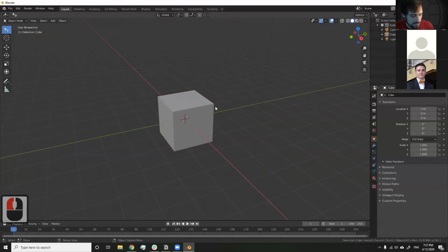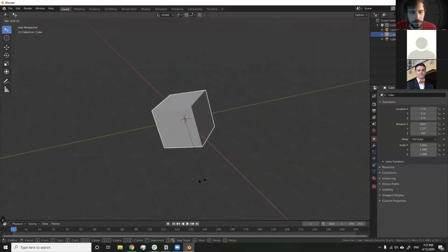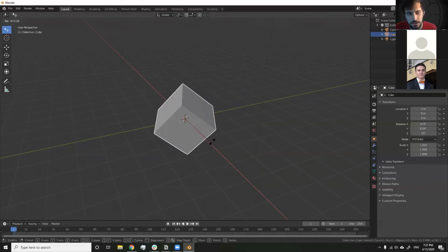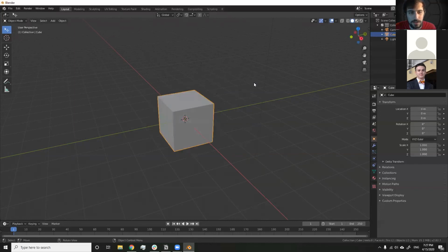The next shortcut that we want to go through is hitting R, which will allow you to rotate an object. So if I just select the default cube and then hit R, it's going to kind of orbit around its center of mass at the center there. You can see that orange point in the middle is its center of mass. It's going to rotate around that. And right now it's not a super helpful rotation, so I can right click to cancel that. Whenever you're doing a tool, if you right click, it's going to cancel whatever transformations you were doing to it.